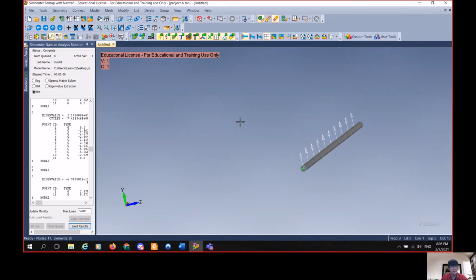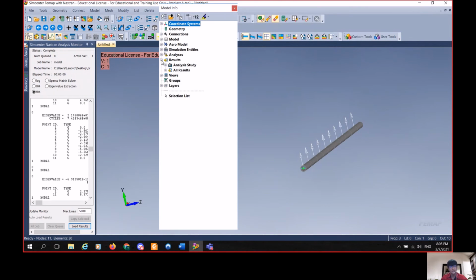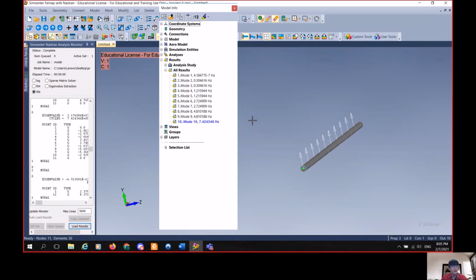After I have done this simulation, I noticed that the frequency that I get from each mode is a bit near to the natural frequency of the new pump, which is 3.33 hertz. So I tried by trial and error many times to fix this problem, changing the thickness of the laminates, the number of laminates, and the different types of material, but it doesn't work. It doesn't show any significant changes in my frequency.